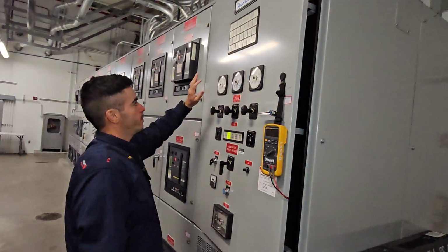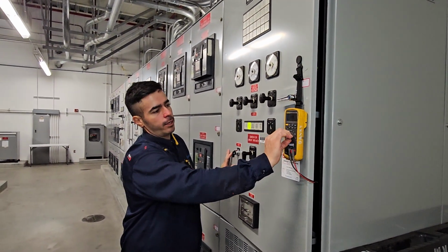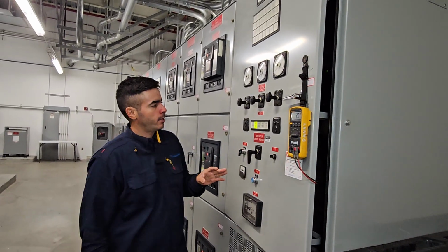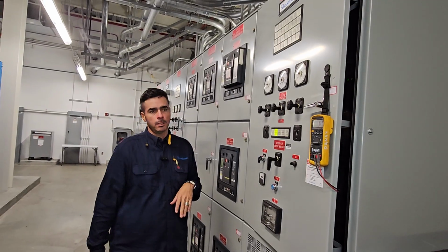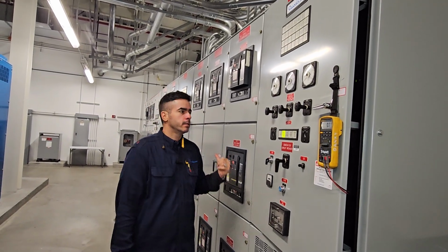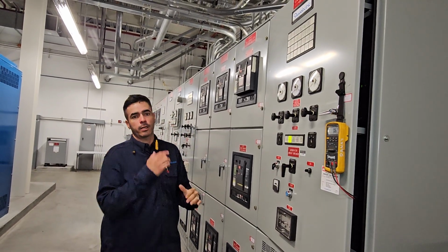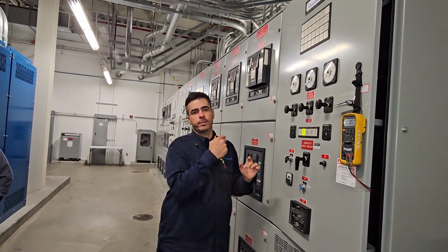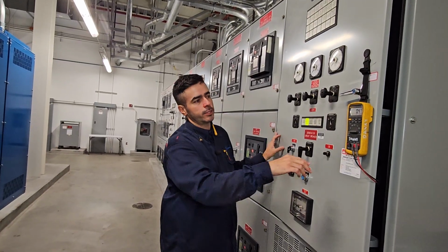All right, I put my meter behind this voltmeter, and I'm going to be looking for AC power. It depends on the system. I can have 120 volts or up to 200 volts. The reason I'm doing this is I want to check the voltage and the frequency. Then I'm going to do the same thing with generator 2 and compare those numbers. I have to match them, kind of. If one of them is too low, I'll raise it up or lower it down. I'll do it anyway, so you guys can see.